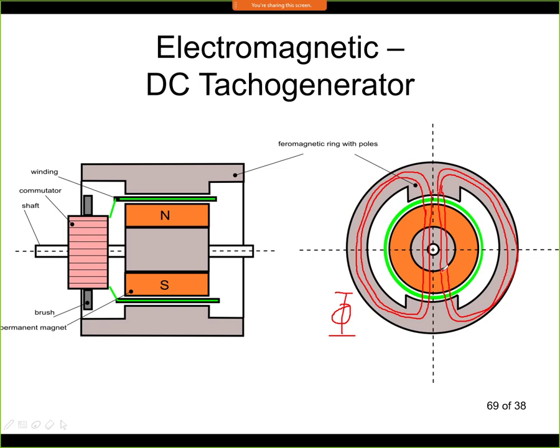In order to make it work, we need the ferromagnetic material also on the rotor side. So typically this is a cylinder of iron, and on this cylinder we have the permanent magnet. It's either in sections or it's really just like a cylinder. This whole assembly is then attached to the shaft. Typically it's a press fit.